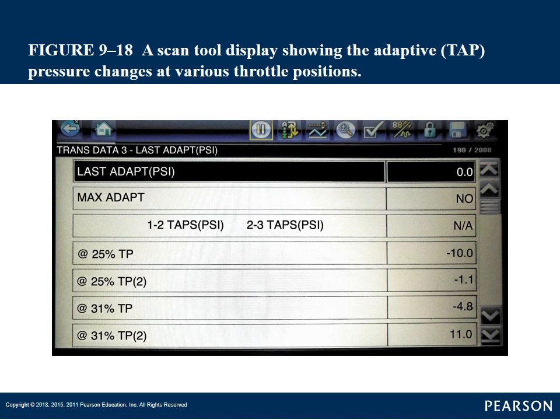So at 10% throttle, which is a light throttle, it's going to take maybe a little longer to shift because they want the shift to be smoother. Then at a higher throttle, they may want that shift to be a little quicker, so we don't slip the clutches as much. If that starts getting out of those parameters, then they'll control fluid pressure to get those shift points back into the parameter, the timing of those shift points.